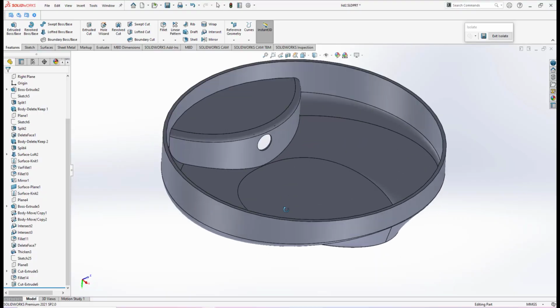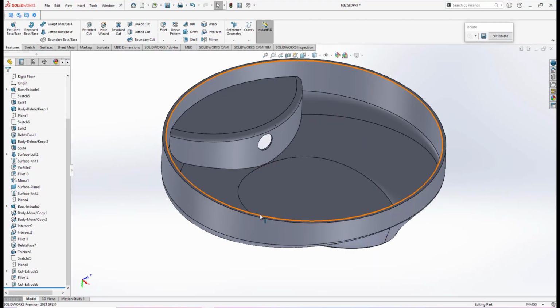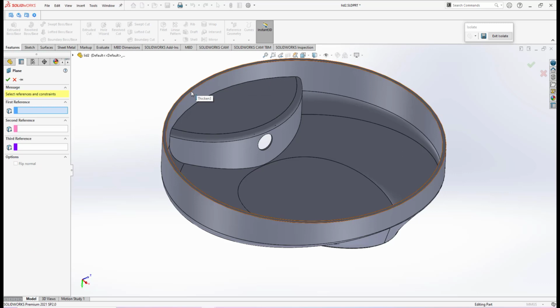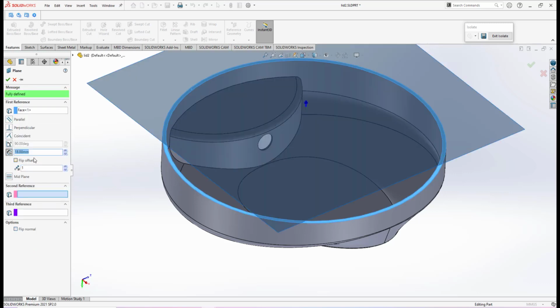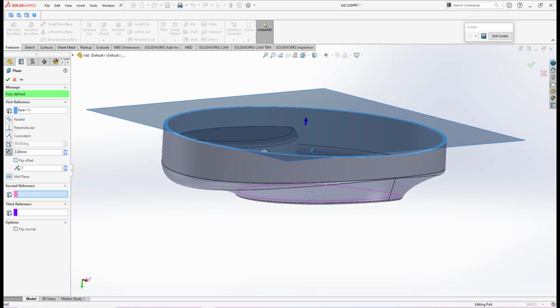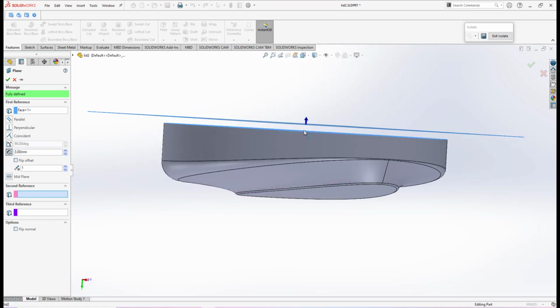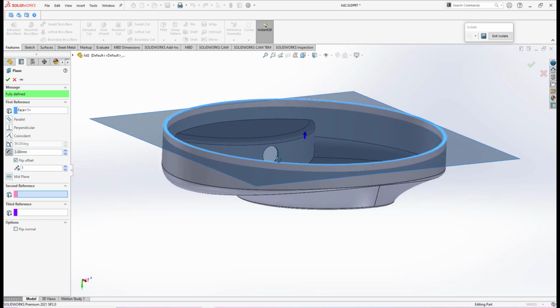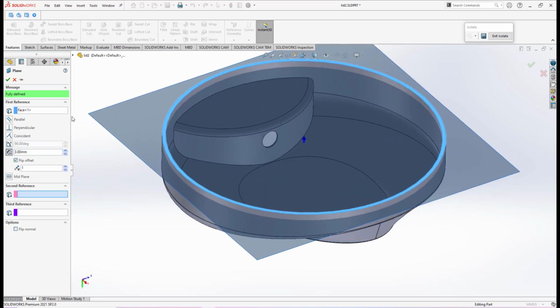I start at this bottom plane here. I make a reference geometry plane, this will be my first reference, and the distance I already measured is 3 from that plane, and the direction is supposed to be inside, so I make a flip. So that will be the plane for the height of the shaft.